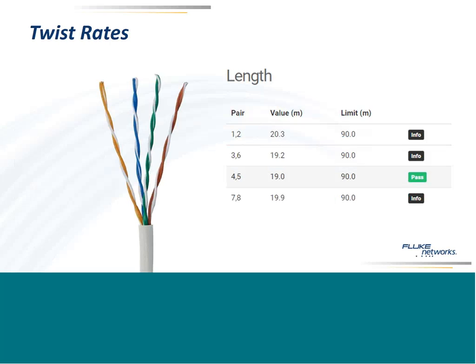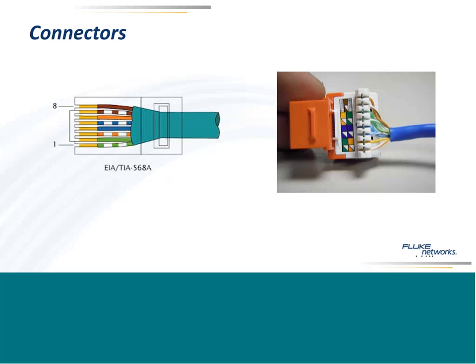Now, with cabling, the twisting really gets rid of almost all the crosstalk. It's really an amazing mathematical certainty that you get rid of most of the crosstalk. But you still get crosstalk in cables. You get a little bit during the cable. The bigger problem is in the connectors. And if you look at this image on the left, you'll see why that is.